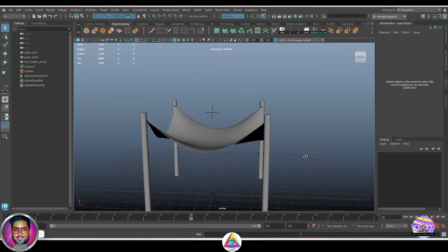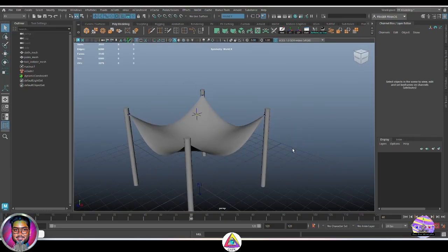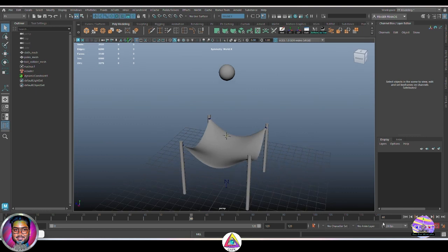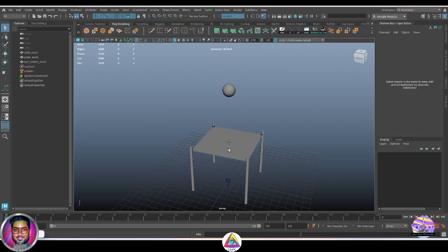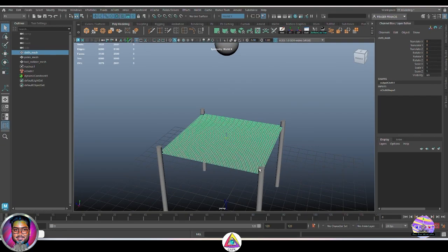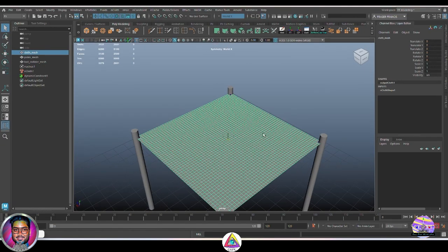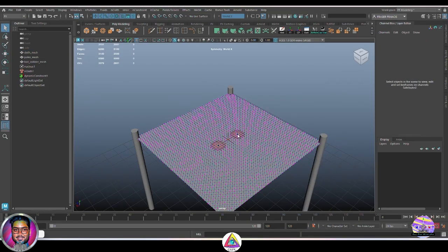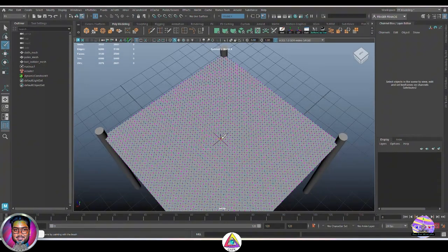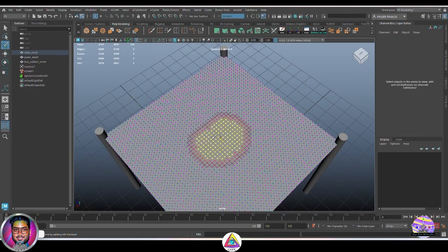Next up, let's create the tearable portion. So the portion of the mesh of this cloth in the center is going to be torn out by the collision of the ball with the cloth. For that, we need to select the portion. We'll go to vertex mode and take the paint selection tool, use the soft selection, and just paint this area, a centrally located circular area, since it's a circular ball. If you want, you can keep a random kind of shape for this also.